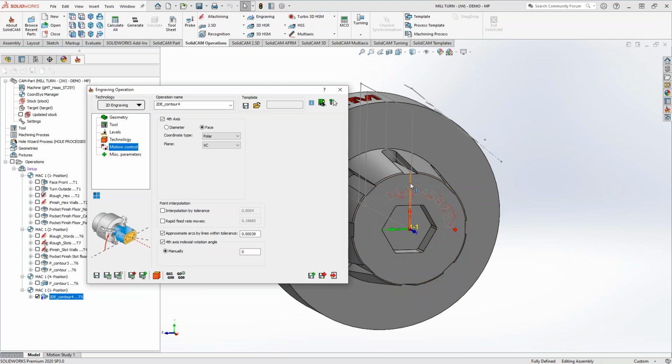I just need it to come over here to the 0 degree plane, and then I have the room to move, the room to do that toolpath. This would literally just output code that rotates it by that much. In this case, let's say, what is that? C90, so 90, and then it's popped up over here, and then I can do my toolpath.